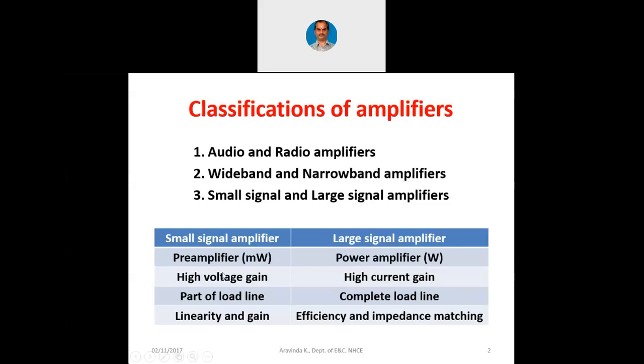Till now, we have been discussing only the small signal amplifiers. In general, whenever we have a complete amplifier box, there can be multi-stage amplifiers. In the beginning, there will be a pre-amplifier. At the output, there will be a power amplifier. To give you an example, in a musical concert or in any such function, when the singer is singing, it goes to the amplifier box, and the mic set will be connected to the pre-amplifier, where it will increase the signal amplitude maybe by 20 dB or 40 dB, let us say with the voltage gain. Now that is the pre-amplifier.